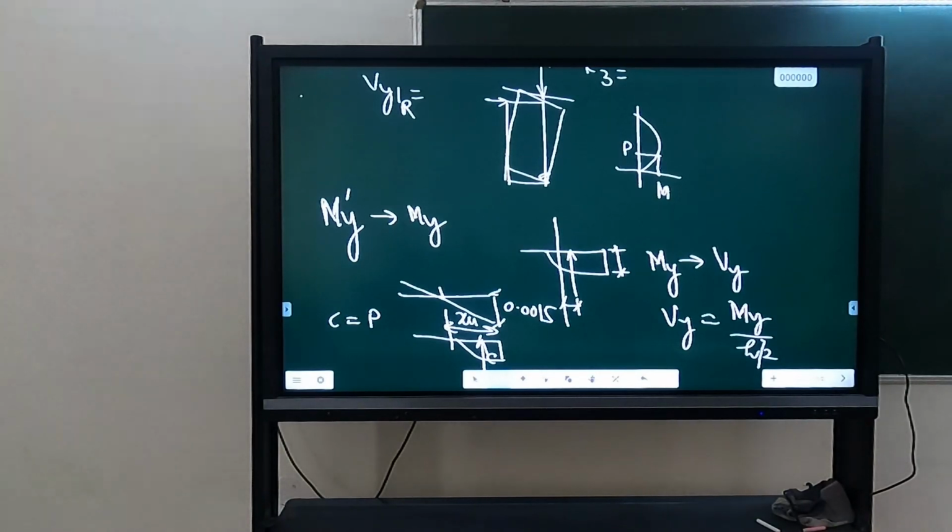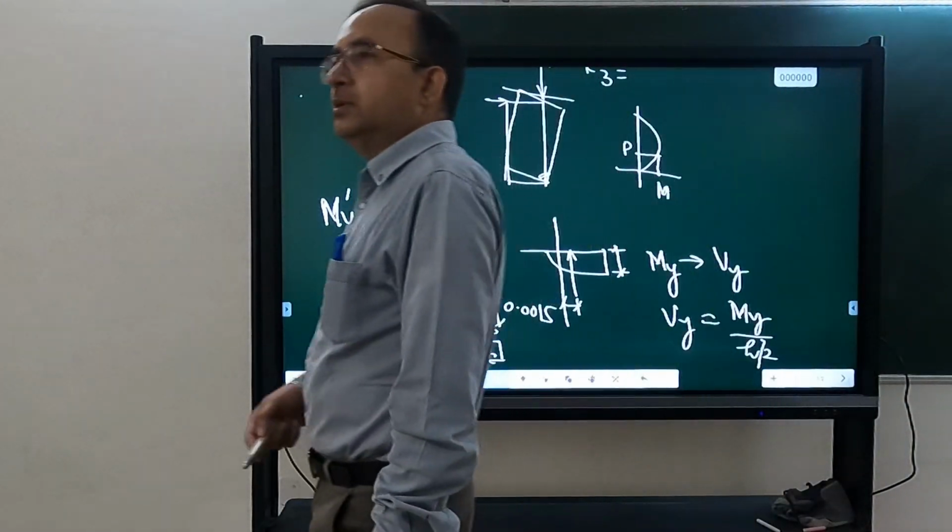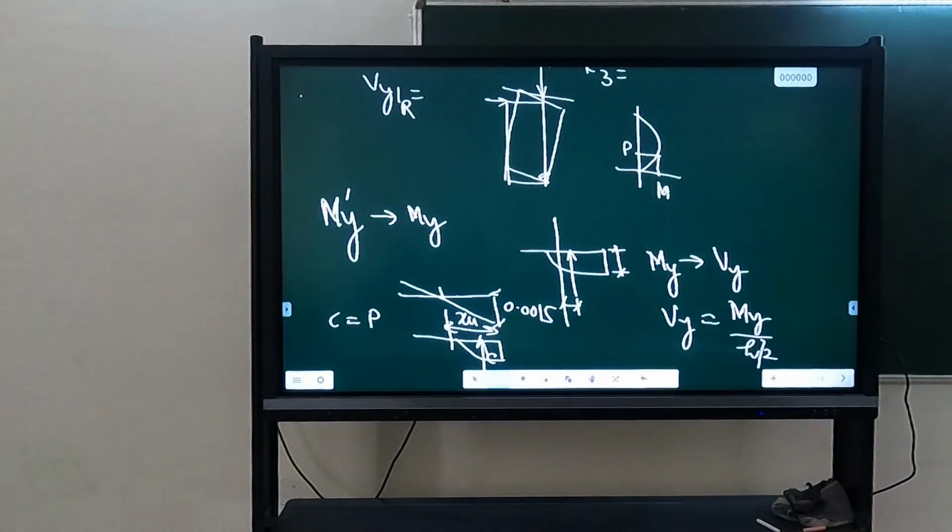Okay. I am asking, sir, that for that stress curve, we are using the equation for RCC as 2 times epsilon upon epsilon 0. Same will be used here. We are assuming that the stress strain curve for concrete and masonry is same. No, so there is 0.002. Here maximum is 0.0015. So that 0.002 also reduces. What is that value? You have done this in case of concrete also. When the concrete fiber was yielding, the strain you have taken 0.0015. And in that case you have calculated C in concrete. How did you calculate? You have integrated it up to 0.0015. Same thing you will do here.